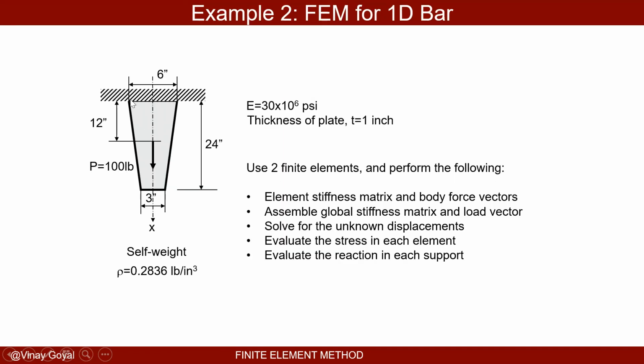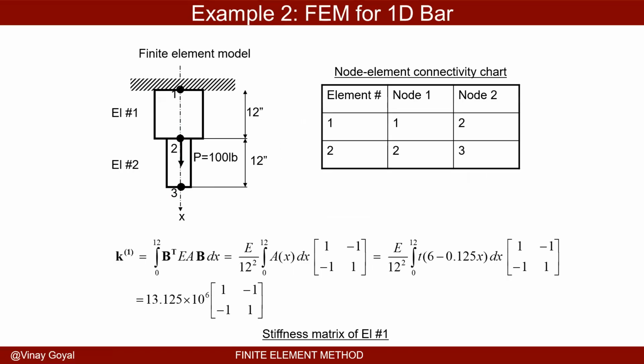So I'm being very, very specific on how I do that. I also decided to model each of these sections as the average cross section for that particular section I divided the domain into. So constant cross section here and here. So for element 1, I have nodes 1 and 2 connected, and for element 2, the node 2 and 3 are connected. Okay, so now I can calculate the integral. And I actually decided to calculate the exact stiffness matrix for an element that has varying cross section. In fact, you can see that here.